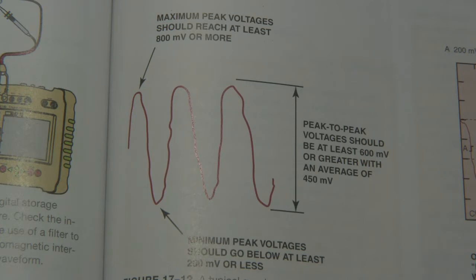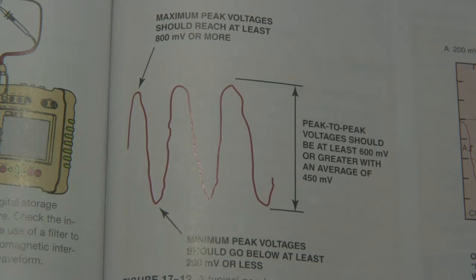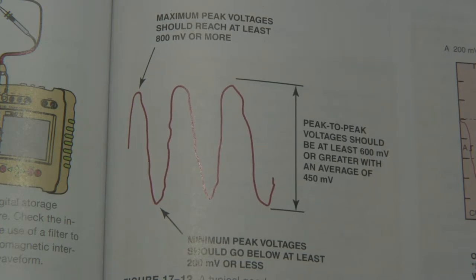Now, when would you want to use an oscilloscope? If a sensor was marginal. And so, what do I mean by marginal? Let's say hypothetically you had a car that was failing for an oxygen sensor performance code. So bank 1, sensor 1, performance. What that code is directing you towards is the oxygen sensor, its switching, its ability to cycle.